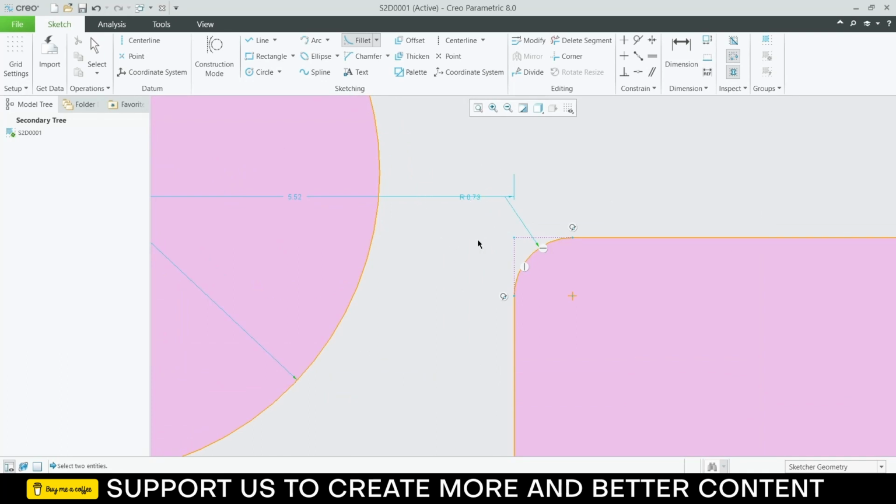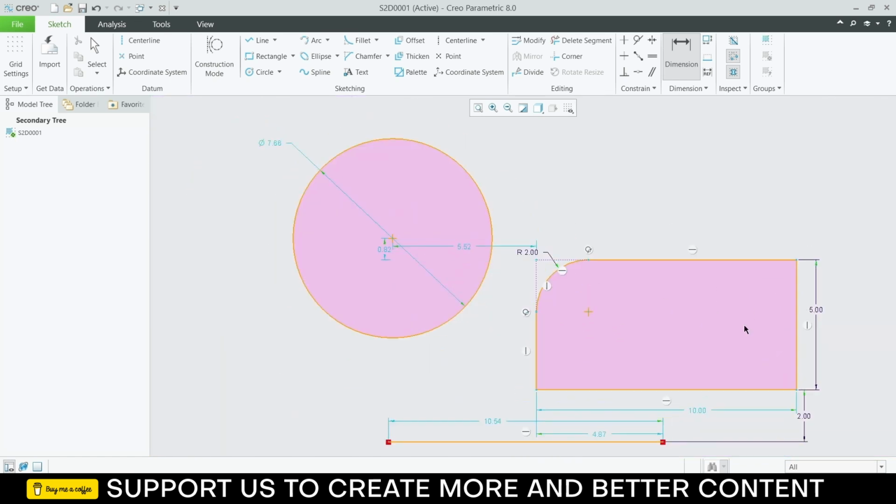Now here is the issue. I am not able to select this dimension. So to select it, what I can do is click on dimension. After that, try to select it. Notice I am able to select it, but I want to edit this value. So what you need to do is double click on it and give it a dimension. Let's say 2. So this is how you can give it.